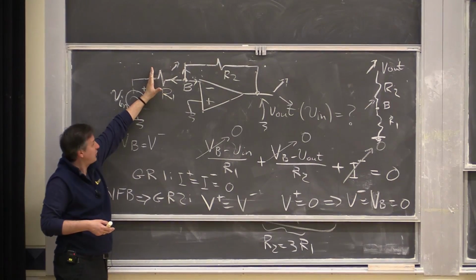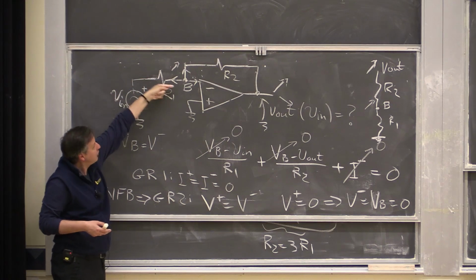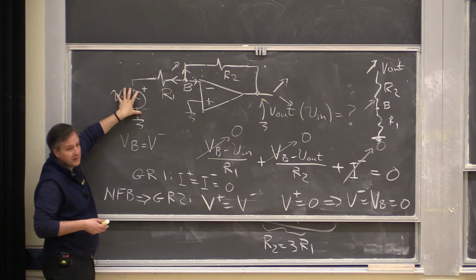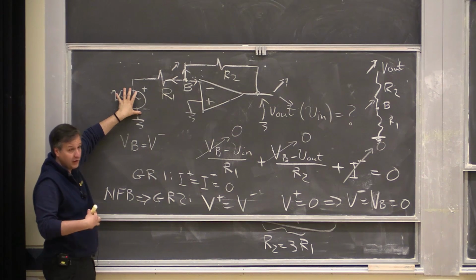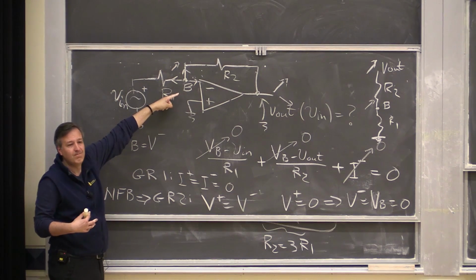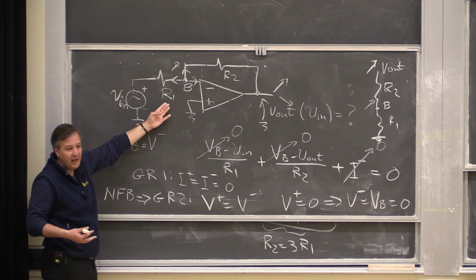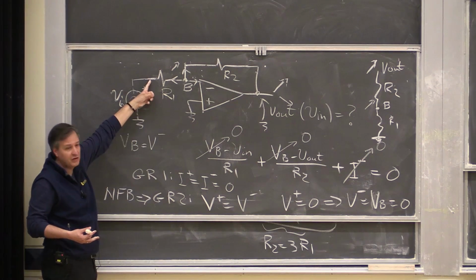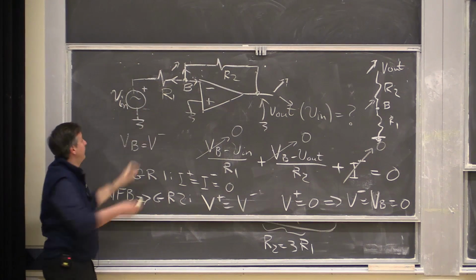This circuit starts with a resistor, right? And there is actually some current flowing from this supply right now, or a signal source, but it could be another circuit, into this circuit. That is called loading. Depending on what the value of this resistor is, that will change the value of this current. Right? This current is V in over R1, right?